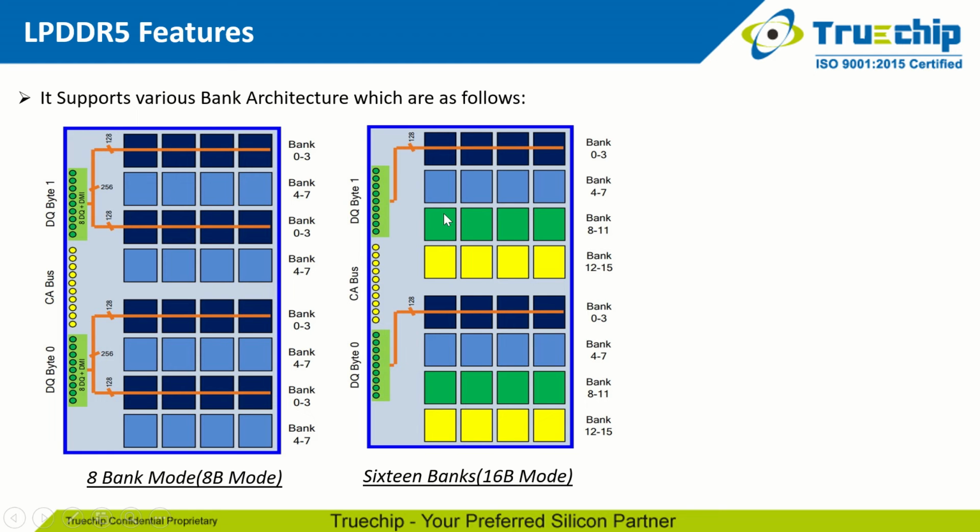Talking about 16 bus length data on X16 pins where the total data to be stored is 256 bits, out of which 128 bits will be stored by DQ byte 0 and another half of the 128 bits will be stored by DQ byte 1 inside the memory bank.